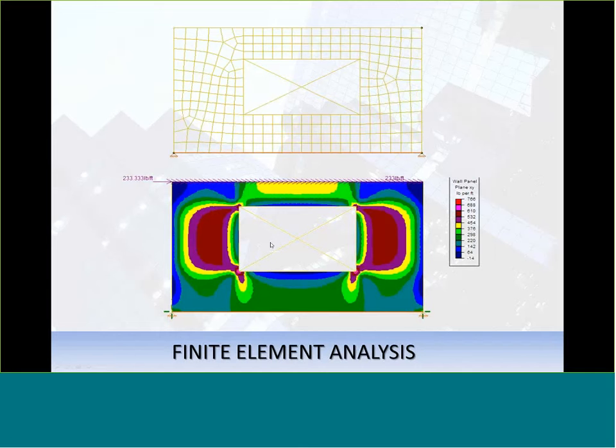but what is a wall element? I just want to refresh your memory on going back to the finite element analysis. What's happening there is we're building this plate mesh internally. So we've got a mesh of plates going on behind the scenes, and you can see from this top, you see all that sub-mesh of plates built in there. Now, if you were to do this by hand, it would be a really difficult and tedious process. And we used to teach folks how to do this all by hand, and you can do that. But what's nice about the wall is this is all internal for you.